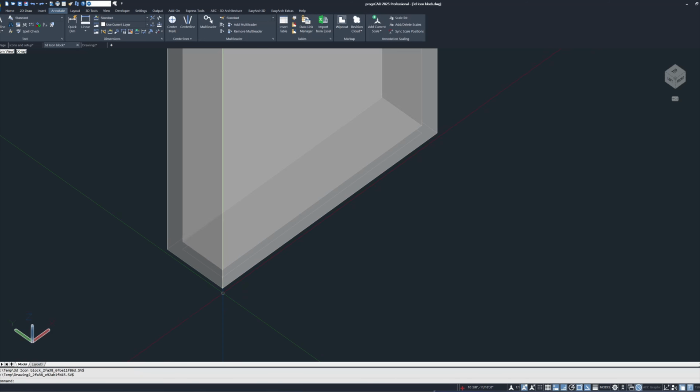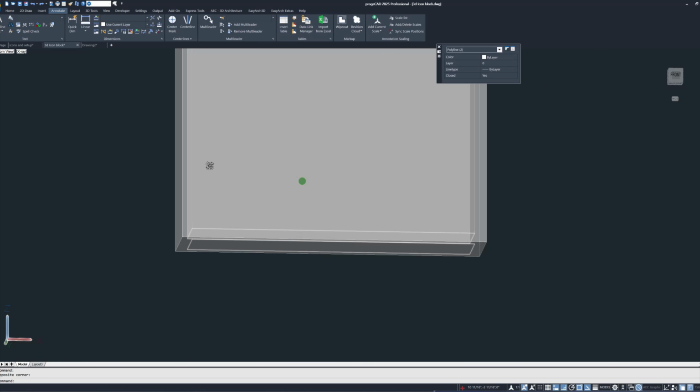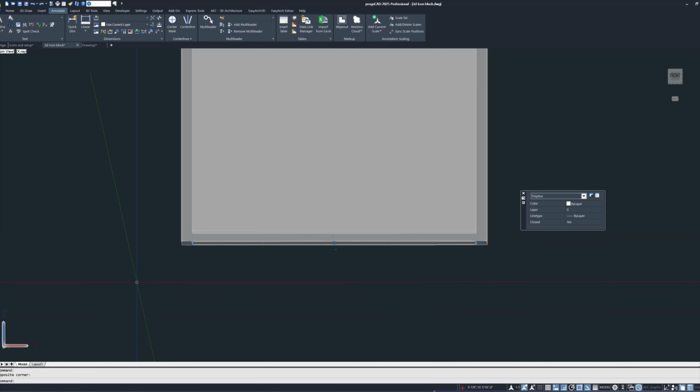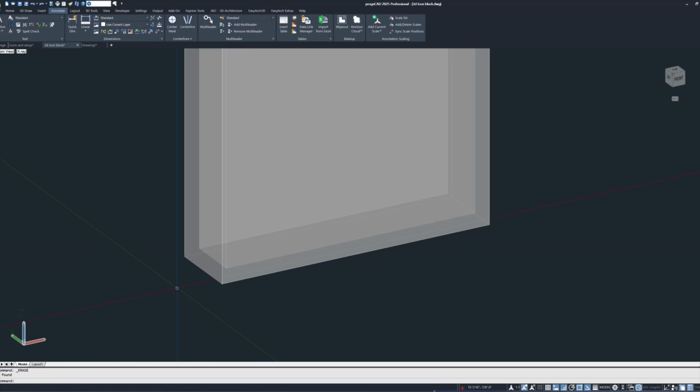There are still two polylines left within the model. Find them using a window, then modify the lines to fit our next parameters. Only the line close to the void space will be needed, so remove the line near the bottom of the box. Press the Delete key. Create a window to select the desired polyline. Move the line up 1/8 of an inch.